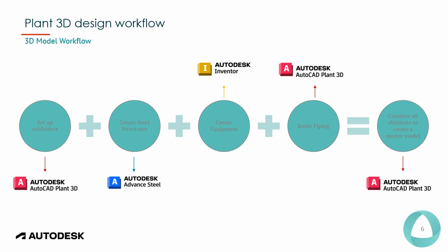On this slide, we are looking at the workflow on the 3D model side of the software. In the 3D environment of Plant 3D, you will start by setting up your folders and all your subfolders, breaking the plant into as many sections and areas as you can.